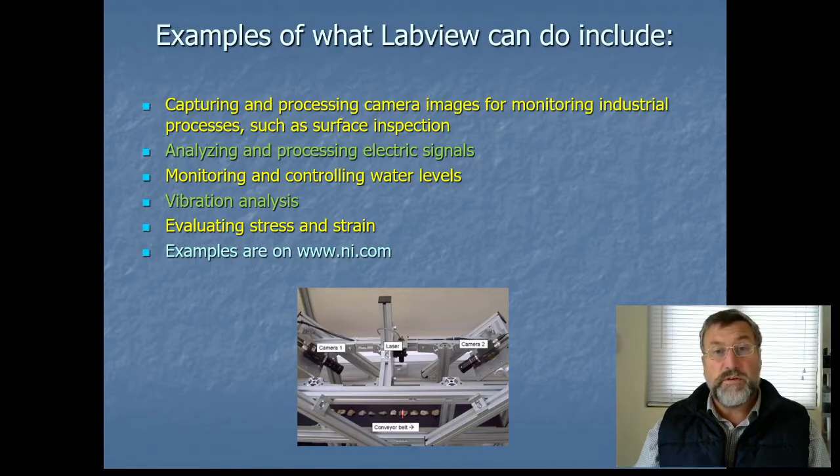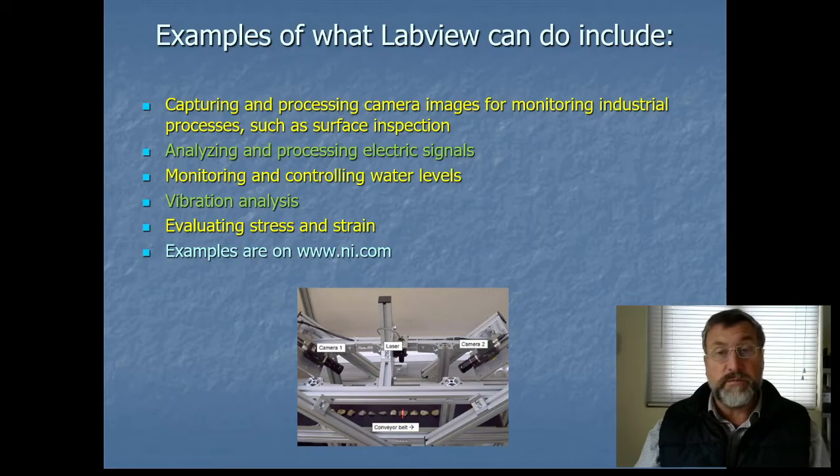And that would be the kind of thing you might use LabVIEW for, because you might have a solar panel for getting electricity. You wouldn't need a great deal of power just for that. And then you're data logging, analysing conditions, especially if you've got a lot of flooding going on. It's pretty important. Vibration analysis. It's the sort of thing where you could have a machine tool with little sensors mounted all over it, and you could be measuring the vibration during different types of cutting operations, for example.